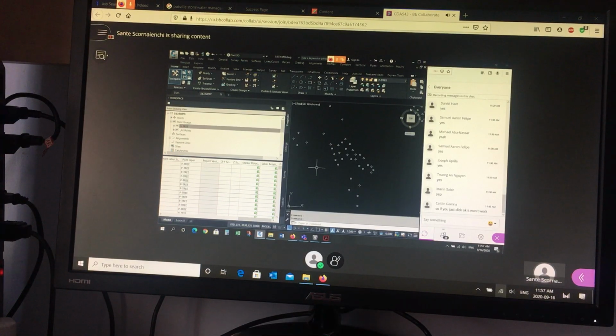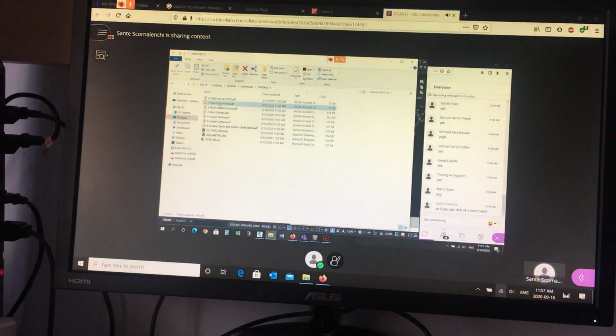So those three items, if we go back, if this has already been created, then all you have to do for your design or drafting work is import the points. And then it'll put everything on the correct layer. It'll put everything into the correct group. And by virtue of the layer you're on, you'll get the colors and line types you want.